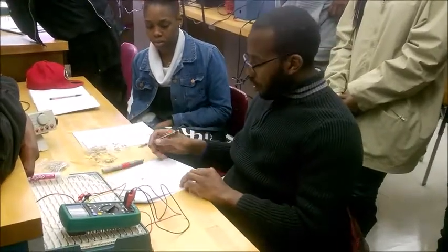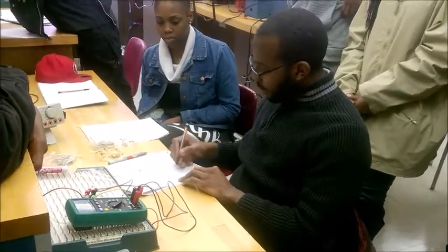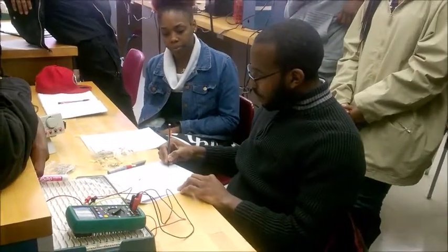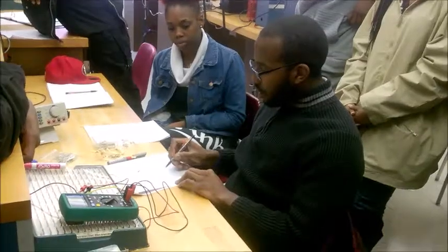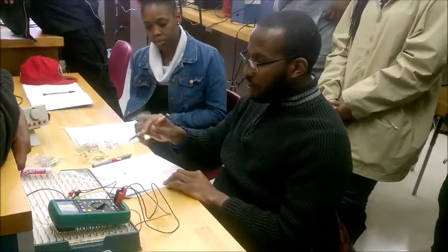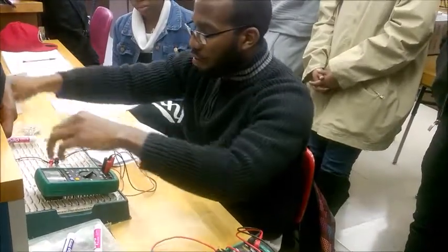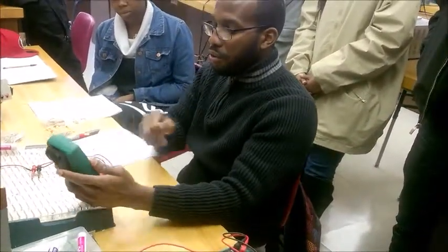Now we're going to use Ohm's law. Again, Ohm's law tells us that current I is equal to V over R. So what is our R? We measured it. We wrote it down. Okay, I didn't measure this one. Okay, I'm going to turn this off. So we're done with our experiment, right? Turn this power off. Let me turn this guy to resistance.